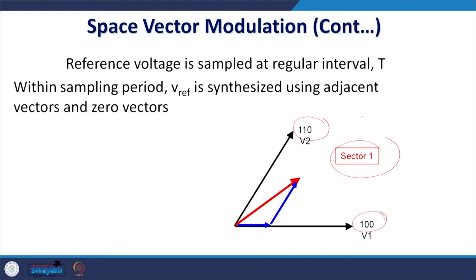So, we can make it like this: if you apply the total voltage vector, that is 2/3 VDC, you will apply this much of this vector V1, ultimately you have to match the reference voltage. Similarly, this will be applied for the time T1, and similarly this will be applied for the time T2, and our task is to compute T1 and T2 rightly.